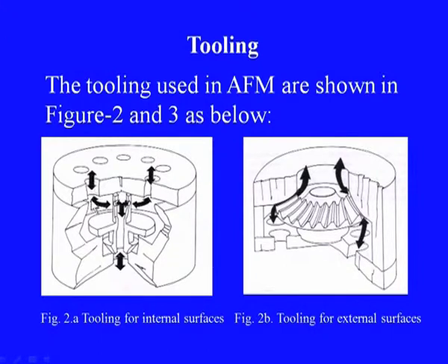So is the case with these internal surfaces. Media is directed through different passages in this solid tooling, and media is allowed to flow through this workpiece, and while flowing through it comes in contact with the internal surfaces of this workpiece, and the abrasives cause the abrasion on the work surface, thereby causing improvement in the